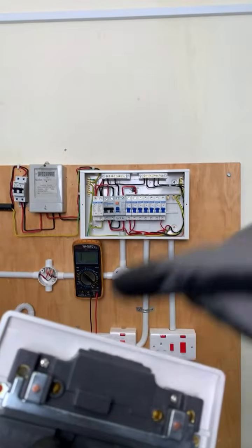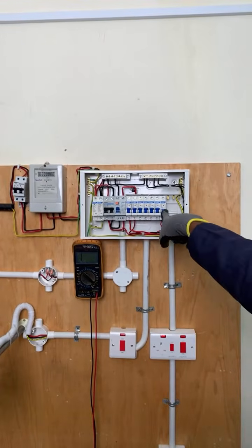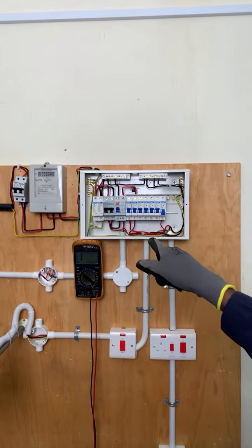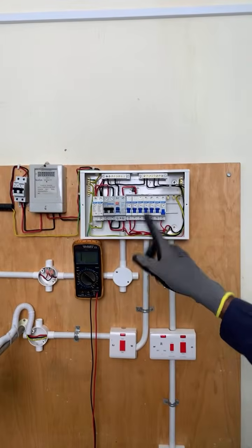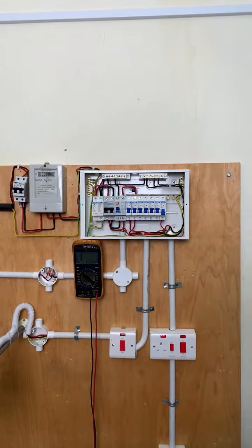But again, that leakage goes back as a short circuit and trips the specific MCB, unless the wiring is poorly done, right? So if the wiring is correctly done, the MCB has to trip because that is also a short circuit. A short circuit does not only occur between the phase or the line and the neutral only. A short circuit also occurs between the line or the phase as well as the earth connection.